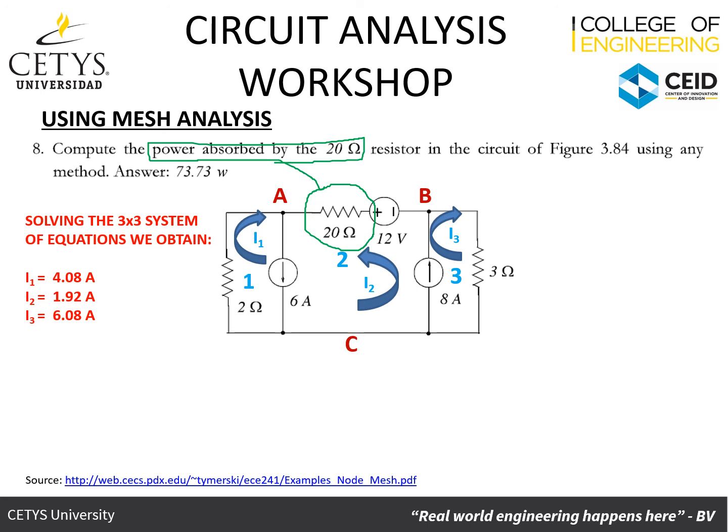And so we've already got the current going through I2, which is 1.92 amps. With these 1.92 amps and the 20 ohms of the resistor, we can calculate the voltage across the resistor, which is 38.4 volts. And we know that power is voltage multiplied by current.